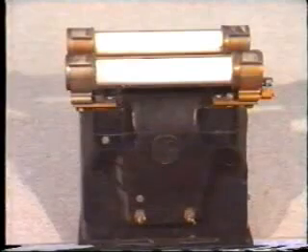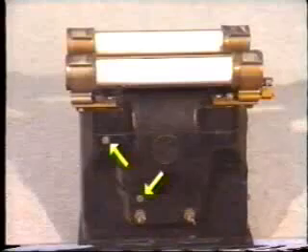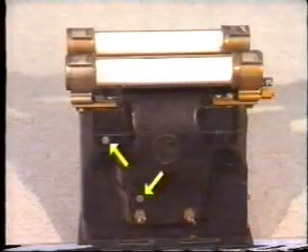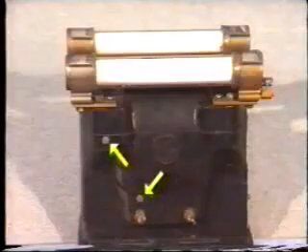The same polarity rules apply for potential coils. The voltage transformer is marked on both the primary and the secondary. Before connecting a relay to a CT, it is advisable to check that the polarity markings are correct. One of the most common methods used to determine polarity is the kickback method.